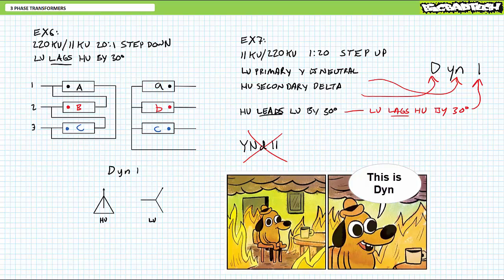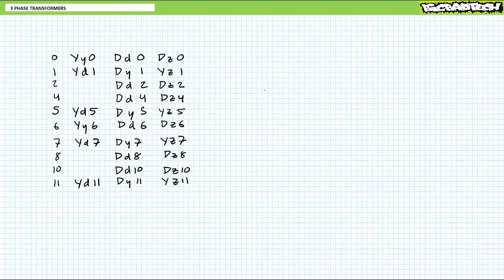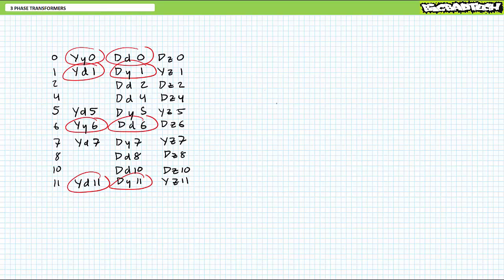If you survive this last example problem with your dignity still intact, you do indeed understand standard three-phase AC transformer nomenclature format. Now, some of you might be worried that this lecture is just about wrapping up and I haven't gone over all 16 recognized arrangements of regular Y and delta configurations in exhausting detail, let alone the additional recognized 10 zigzag bonus configurations. The reason I placed a lot of emphasis on the 0, 1, 11, and 6 groups in the examples is because that's what you're most likely going to run across in the field, and only in the oddest of odd occasions will you ever run into their mutant cousins.